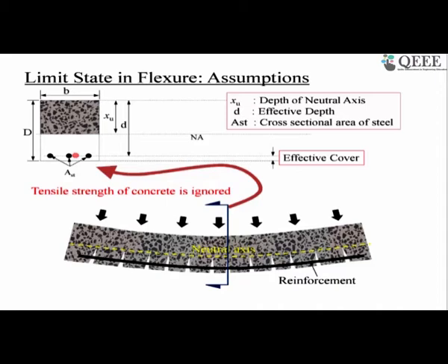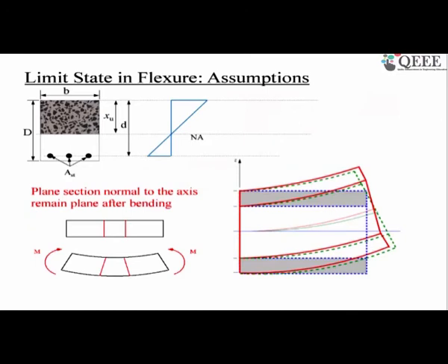The total cross sectional area is the sum of the bars. Those who have had a course on strength of materials and mechanics know the Euler-Bernoulli beam. The Euler-Bernoulli beam assumption is this: consider a beam here. When this beam deforms, suppose these blue dots are a cross section. After deformation, this section actually takes this shape. So this section, which was initially plane, does not necessarily remain plane after deformation, and this is true when the beam undergoes very severe deformation.